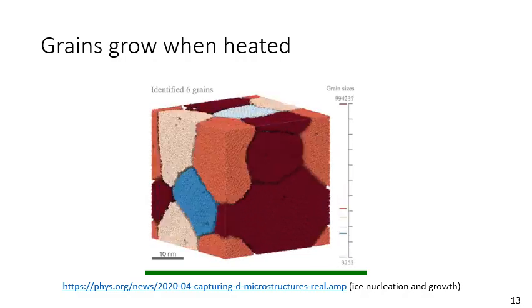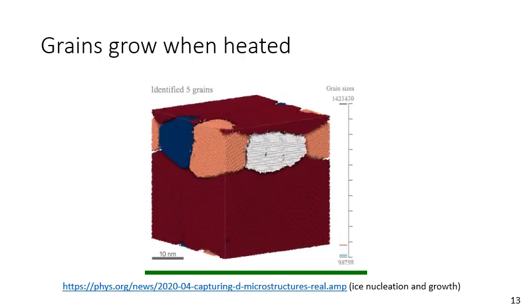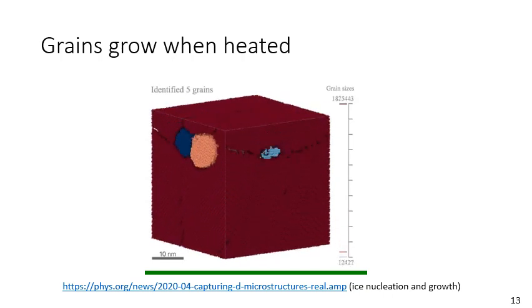So let's play the simulation. Here's the nuclei. Now a lot of grains are growing. They're running into each other. Now the material has been saturated with grains, so the grains are growing competitively to one another as the temperature goes up. And we're going to stop it here, imagining that this is our final grain structure.